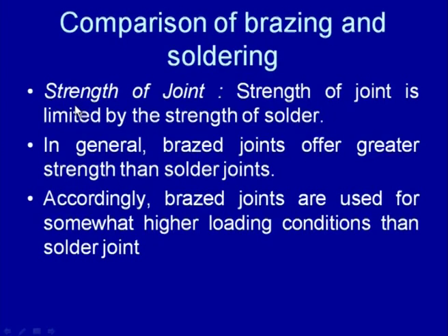If we compare brazing and soldering joints with respect to strength, then in soldering the strength of the joint is limited by the strength of the solder, while in brazing it is the strength of the brazing material being used. Since brazing materials are stronger than solder material, braze joints offer greater strength than solder joints, and therefore braze joints are used for higher loading conditions than solder joints.